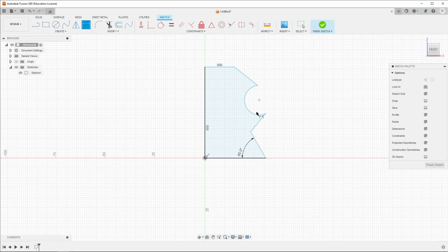There it is. The radius of this circle will be 8. I will make a construction line that is going to be tangent to this circle. So from this point this way. Then I'll keep my construction line and hit escape. It's not tangent officially, it is horizontal. The line is horizontal, but to make sure these are tangent, I'll use the tangent constraint. So I'll select the line, I'll select the circle, and there it is forced, and that stretches this.